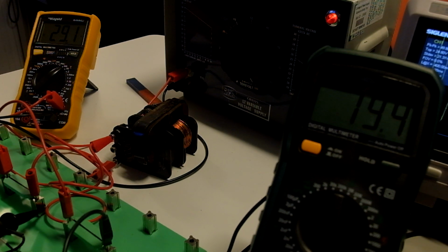So what we've got now is we measure the V in as, we'll call it, 29.0. The current is 19.4 milliamps. The current's a lot smaller because the opposition to current flow is a lot bigger. The voltage across the resistor is 6.3 times 0.0194, which is pretty tiny, just 0.122. We can ignore that. So essentially the voltage across the inductive part of the coil is 29.